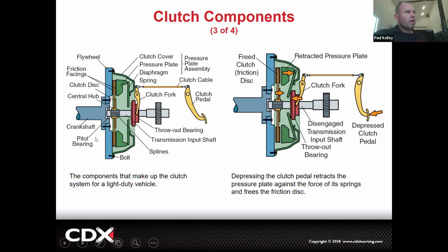So right here, we got the crankshaft in blue. You can see these bolts right here. These bolts bolt the flywheel to the actual crankshaft, right? So those bolts tend to be pretty high torque. They tend to be pretty tight. On a Toyota, a lot of times you'll see those and they'll be 12-point bolts. Cool. So there's that issue.